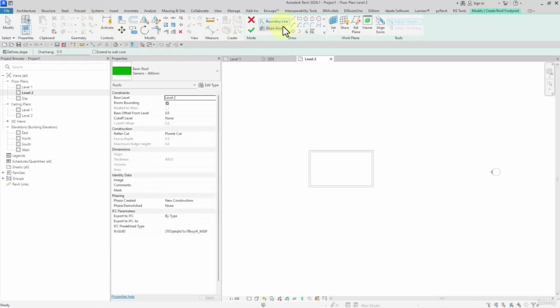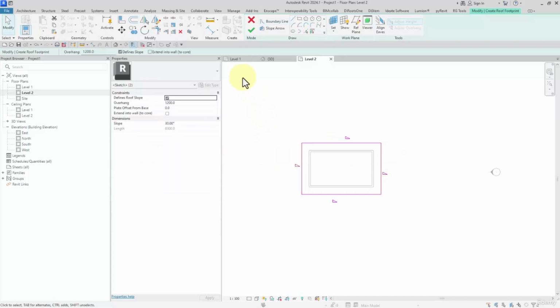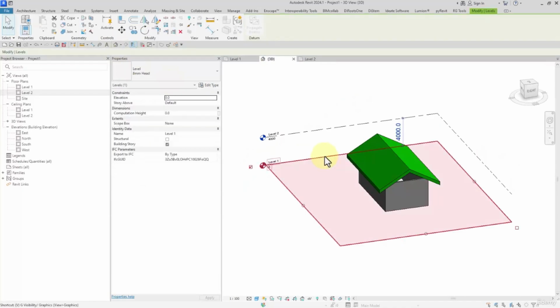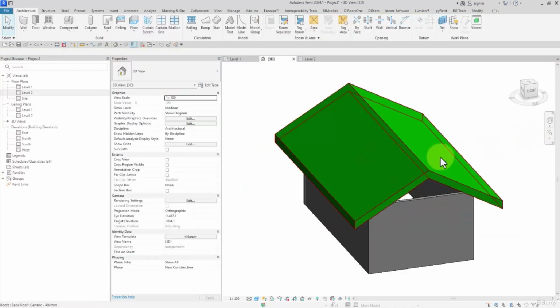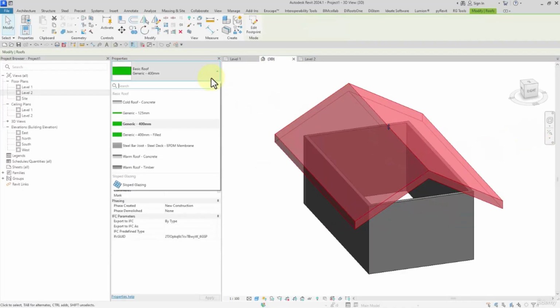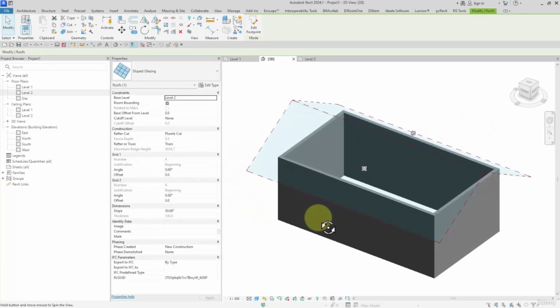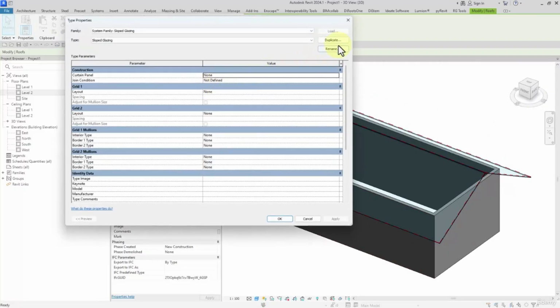Anyway, we open level 2 roof 5 footprints, peak wall using overhang 1200 millimeters, and then we draw the sloped roof this way. Okay, then from now on, for continue, we modify to a slope glazing. After this, I open edit type, I duplicate a new type, roof 01.